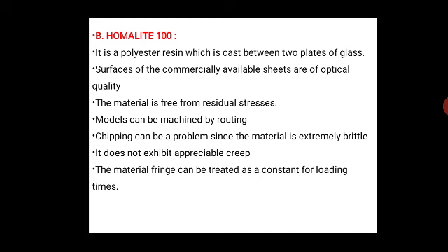Therefore, this material exhibits both low material fringe value and low sensitivity index, and along with this it has another property: high fringe orders can be achieved without fracturing the model. This is the advantage of this material.